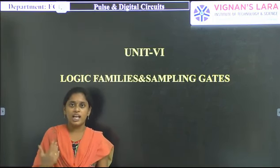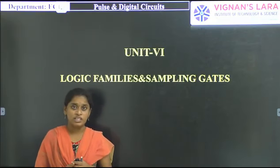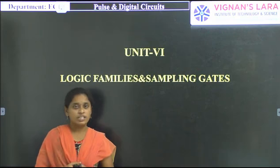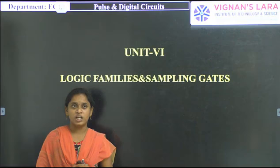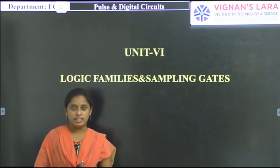So in our day-to-day life, why is it mostly used? Because compared to all the saturated logic families, this logic family is very much faster. That's why the TTL logic family is the most advantageous, the mostly used logic family. Coming to the non-saturated logic families, they can be divided into two types, that is Schottky TTL and ECL.